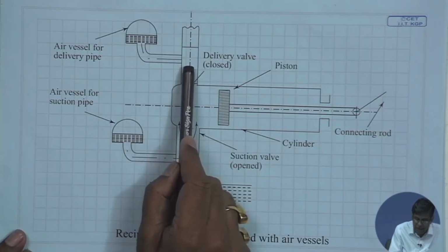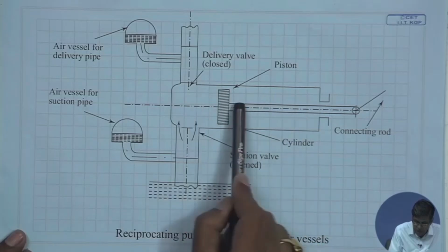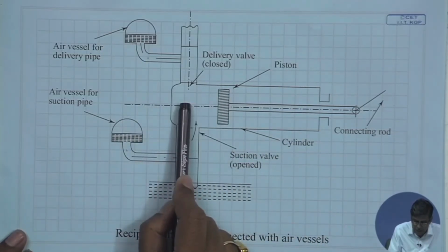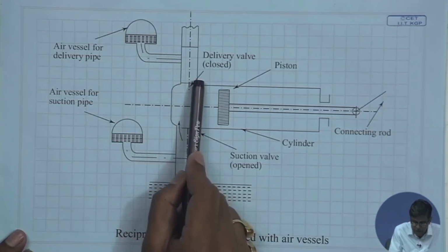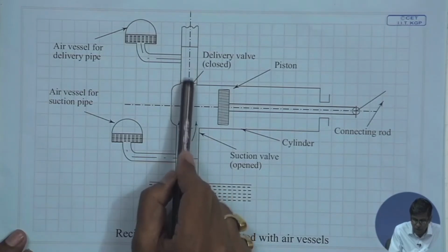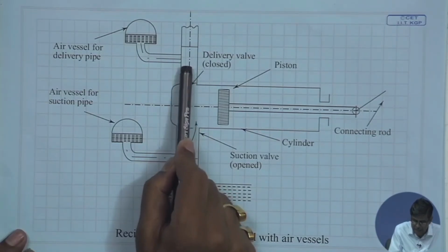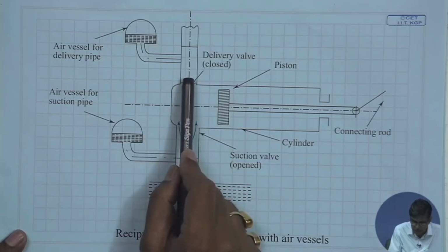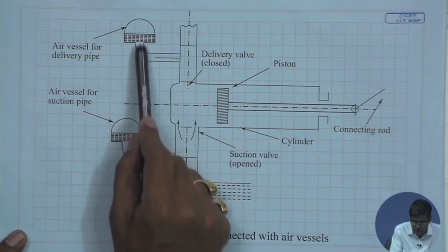So, additional discharge goes here in the initial part, and where the discharge rate is less at the end of the delivery stroke, then the water comes through this. So, therefore, in this part of the pipe, the discharge is fluctuating more at the initial part in consideration of acceleration rate and less at the latter part of the delivery stroke in consideration of its deceleration. But in both the parts, this acts to absorb and release water.